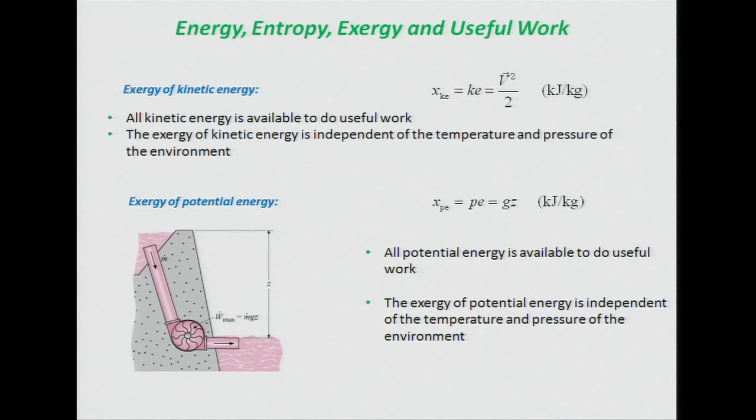Let's just look at some familiar forms of energy. Everyone knows that a half V squared is the kinetic energy per unit mass. All of that kinetic energy is available to do work. So kinetic energy is its own exergy. The exergy of kinetic energy has the same value. Now that doesn't guarantee that when you convert it you'll convert it that efficiently, right? You may waste exergy in the process, but it's all available.